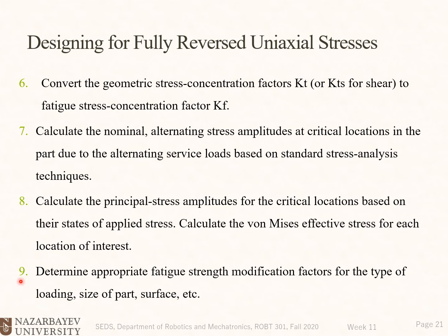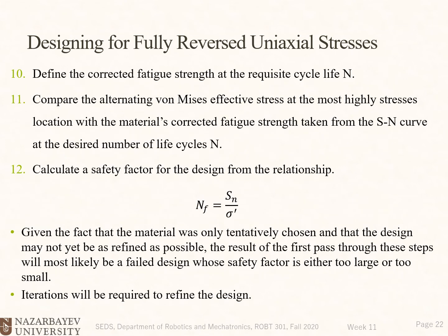9. Determine appropriate fatigue strength modification factors for the type of loadings, size of part, surface, etc. So you remember those reduction factors, modification factors. So we need to find those and apply them to the fatigue strengths. 10. Define the corrected fatigue strengths at the requisite cycle of life N. So find the real